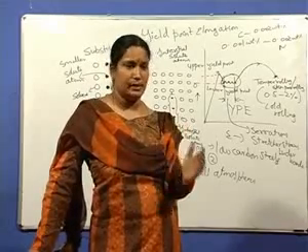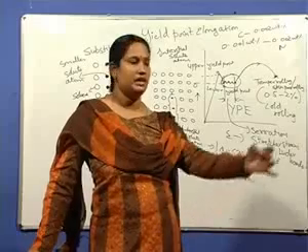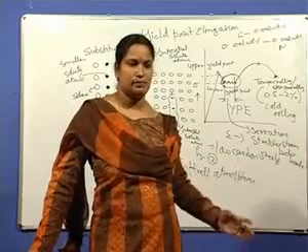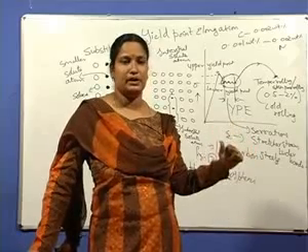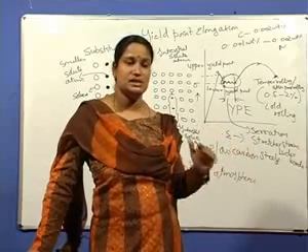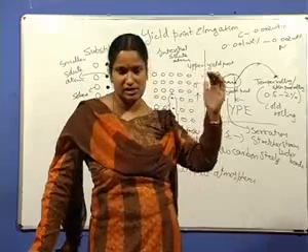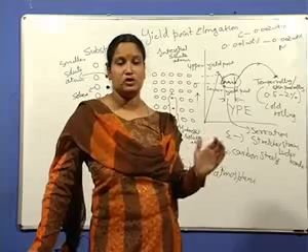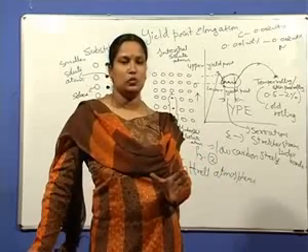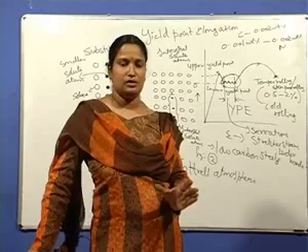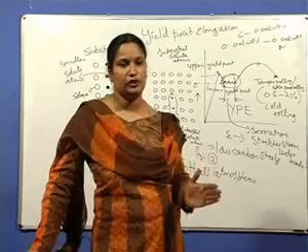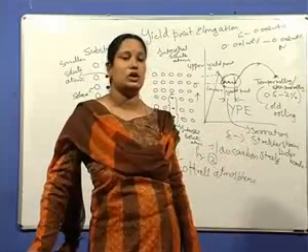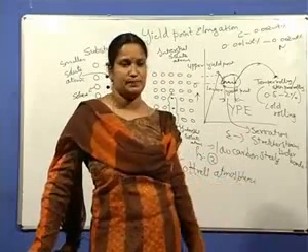But even after temper rolling or skin pass rolling, if the material is left at room temperature for a few days, the reappearance of the yield point phenomenon is seen again at slightly higher stress, because of room temperature aging. This is known as strain aging. This increases the strength of the material, but the defect, the stretcher strains, is not eliminated. It reappears.